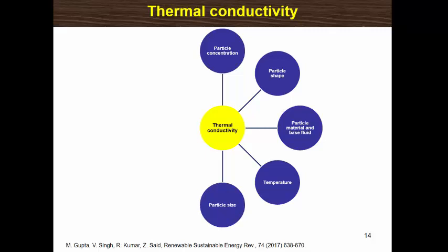One of the important physical parameters which play a major role in nanofluid thermal property and the stability is the nanoparticle size. Based on the published experimental data, the thermal conductivity of nanofluids increases with decreasing particle size. Some additives, such as surfactants, are used to keep the nanoparticle in suspension and prevent them from agglomeration. Thus, they are expected to cause thermal conductivity enhancement of nanofluids. Most of the reports show that the optimum concentration of additive will strongly enhance the effective thermal conductivity of nanofluids.